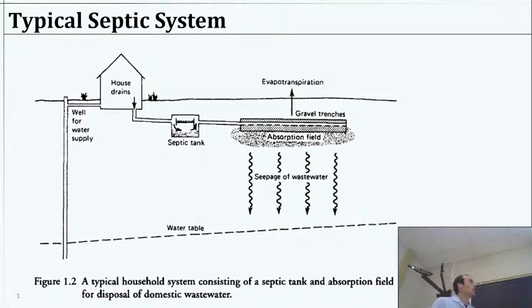Okay. So last time we talked about septic systems, we kind of covered the basics, a bit about the design. Primarily, we need the tank itself to remove solids and digest the solids so we don't accumulate solids too quickly. And fortunately, bacteria can do that pretty well. And the types of bacteria and the types of chemistry that happens in the anaerobic setting works pretty well to do just that.